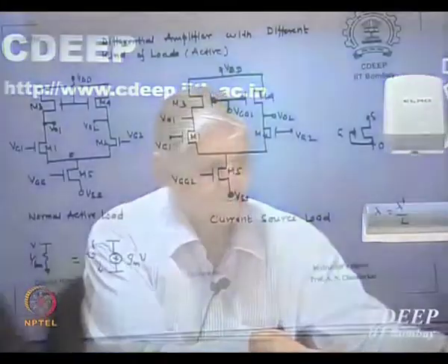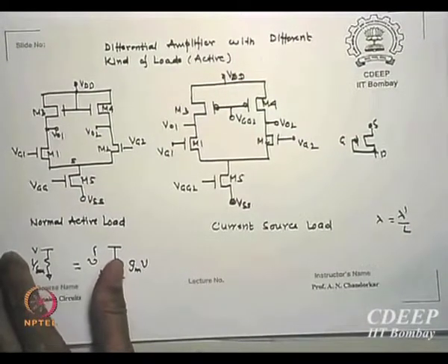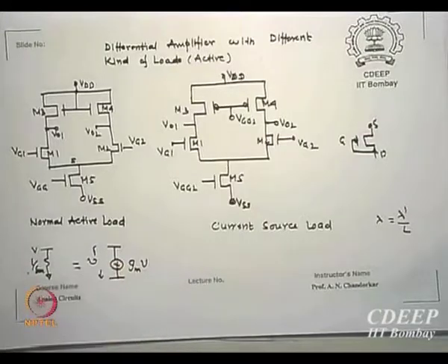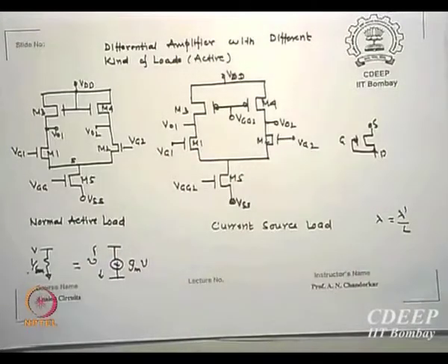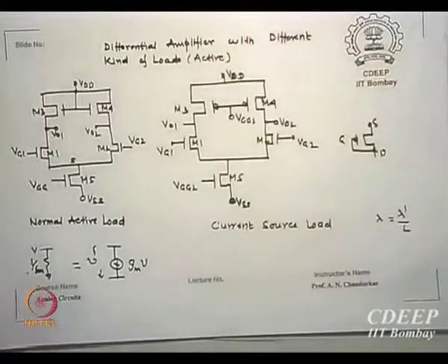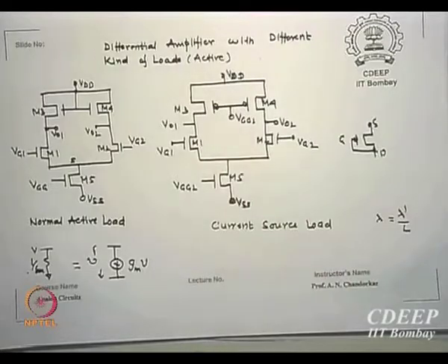current sources itself. That circuit I will not solve, you solve. Which one? The first circuit which I showed you the first time. If these are current sources M3 and M4, what will their resistances be? Will GM appear in this? No, it will not. This is an equivalent R, and this is an equivalent R. The easiest way to solve is this circuit. Is that correct? This is RO3, this is RO4. So it is very easy to solve a current source load. Is that point clear? If these are simple resistors, then we already solved the diff amp case with two simple resistors. So this is the case.